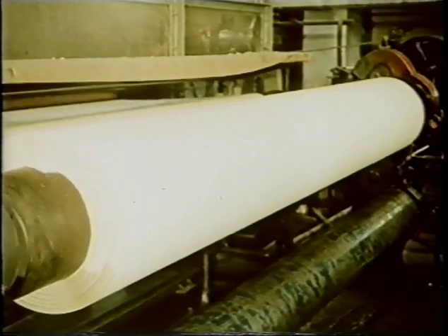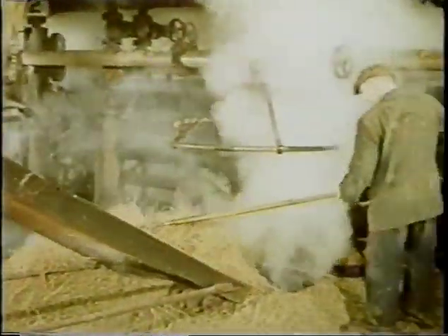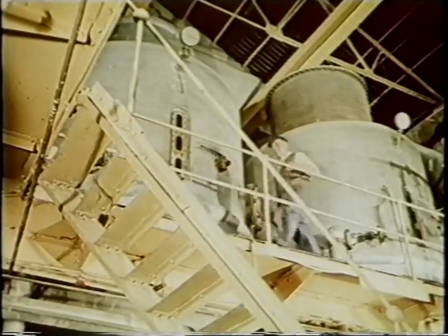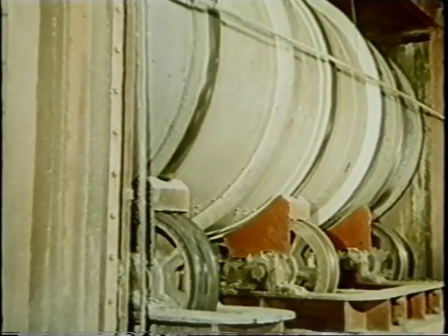To consider the part played by the soda ash, we must go back to the digesters. Out of these, besides the pulp, comes spent caustic soda liquor, containing many impurities. To make the process economic, the caustic soda must be recovered. First, it is thickened in multiple effect evaporators, then pumped into a rotary furnace.